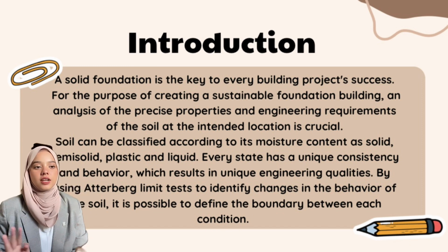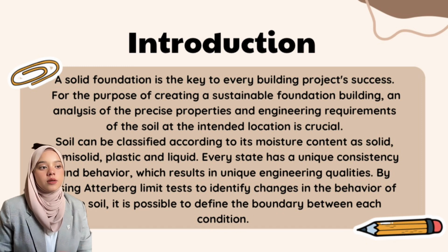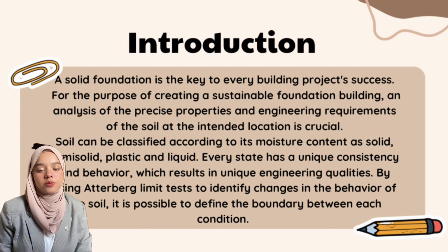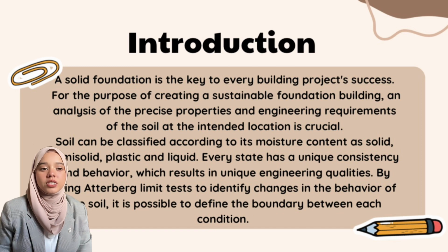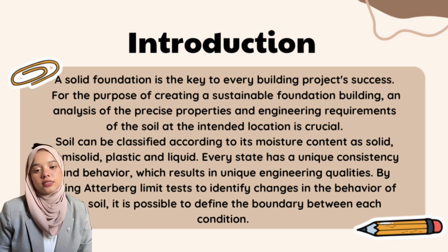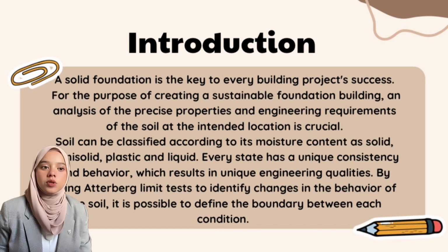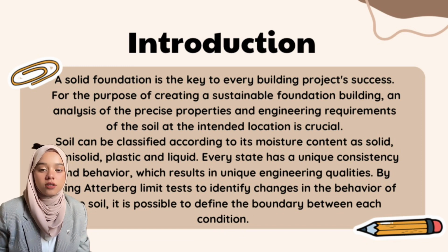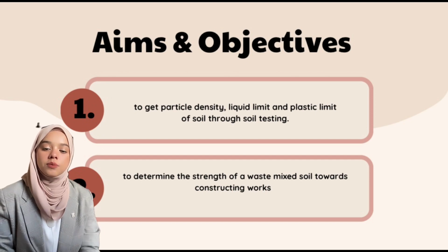Also, soil can be classified according to its moisture content as solid, semi-solid, plastic, and liquid. Every state has a unique consistency and behavior, which results in unique engineering qualities. By using the Atterberg limit test to identify changes in the behavior of the soil, it is possible to define the boundary between each condition. What is the aim and objective of this mini project?